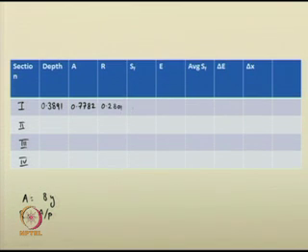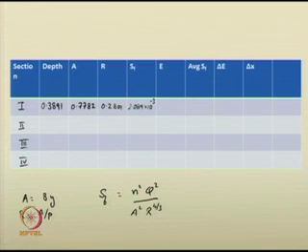The corresponding energy slope SF is obtained as n squared q squared by A squared R to the power of 4 by 3. This value is coming around 2.0819 into 10 to the power of minus 3. Your energy E is nothing but y plus q squared by 2 g A squared.